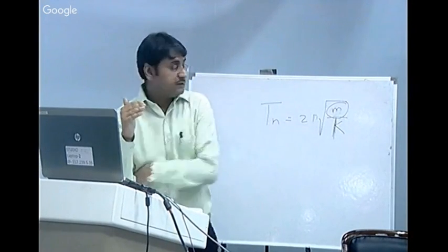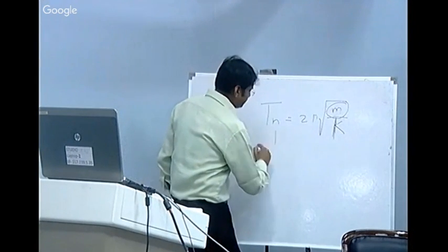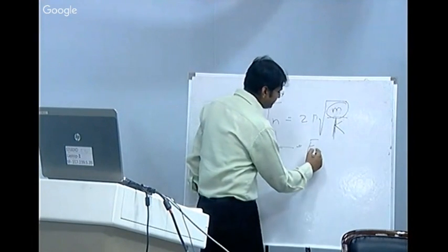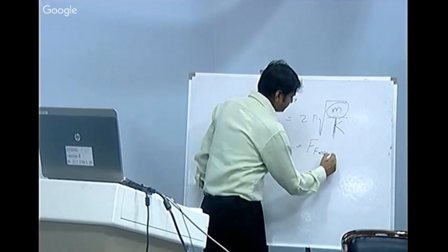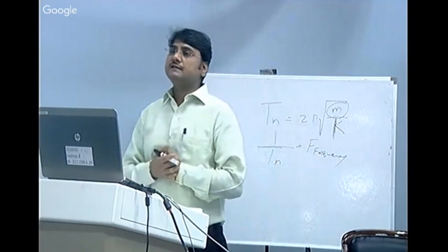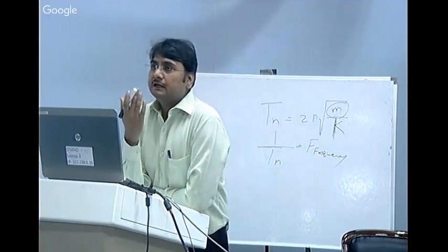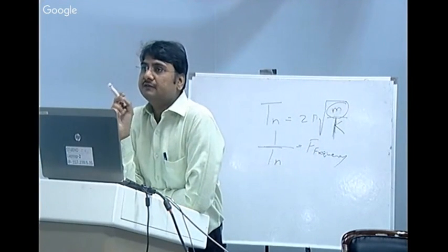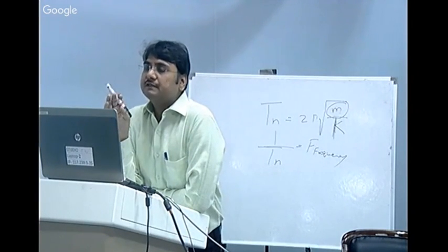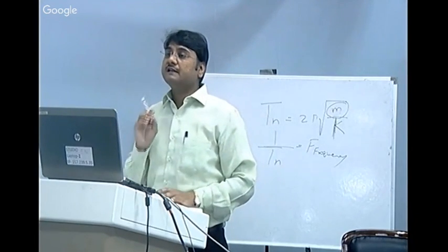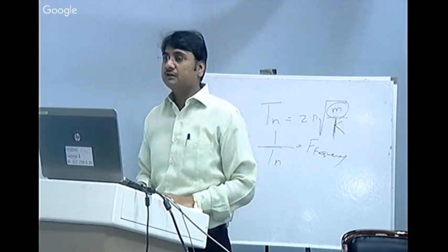Now the inverse of this time period, 1/Tn, is called the fundamental frequency. Fundamental frequency is the reciprocal of the time period. If the time period is more, the fundamental frequency is less. If the time period is less, the fundamental frequency is more. Every structure has its own frequency. And what is this frequency? At that frequency, the structure resists very little during any oscillation. The structure will not resist the oscillation.